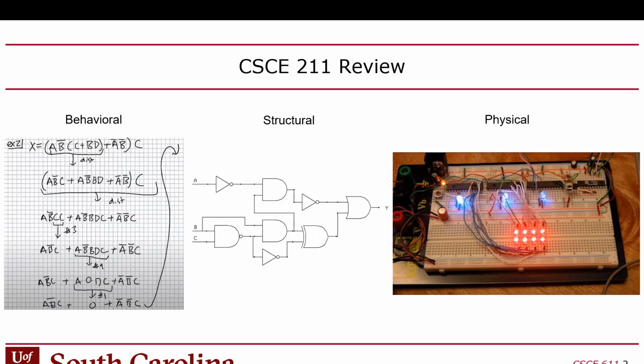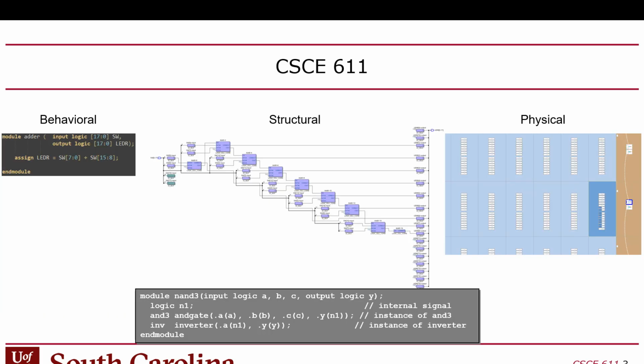Those 7400 chips usually have, for example, 4 AND gates. So each one of those chips has 4 gates on it, and you have to decide which of those 4 you want to use for each of the gates in your structure, in your schematic. Does that make sense? Same thing with a circuit board design too. When you lay out a circuit board, you have a schematic, and then you have to place the footprints for each of the modules on the schematic onto the physical board layout, right? Okay. So yeah, I think I showed this last time.